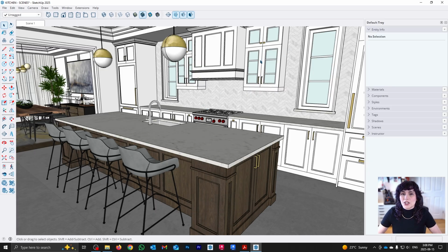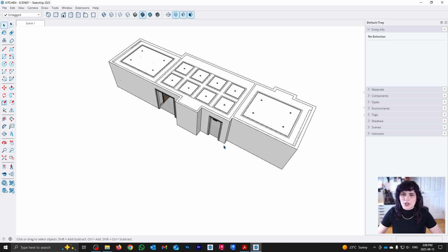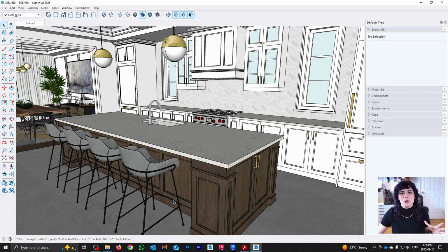And the first and most important thing that they're going to do is remember our camera position and what our camera is looking at. So for example, if I come here and I'm working and doing this and doing that, when I want to return to that previous scene, all I have to do is click on my scene and zoop, it's going to bring me back. So in and of itself, if this is all scenes would do, I would already be like, this is a really good tool. Because again, this is going to mean that you can set up as many views of your project as you want to, for a presentation, for construction documentation, for whatever it is that you're putting together. And then you're going to be able to just quickly cycle through them instead of each and every time having to set up your camera and move it and adjust it and whatnot.